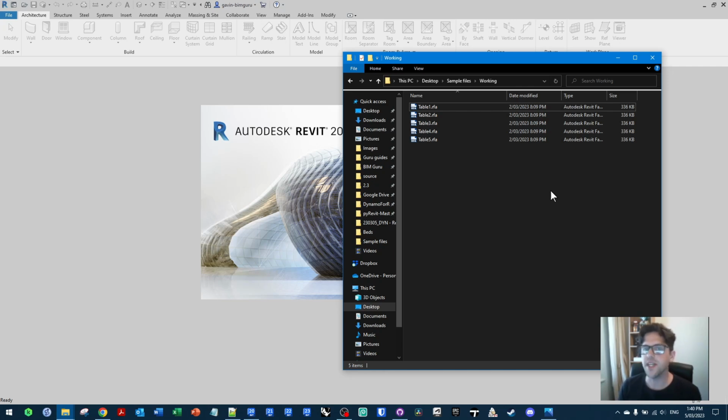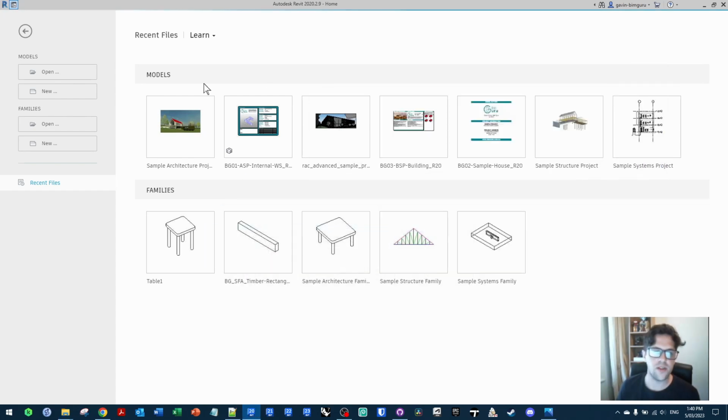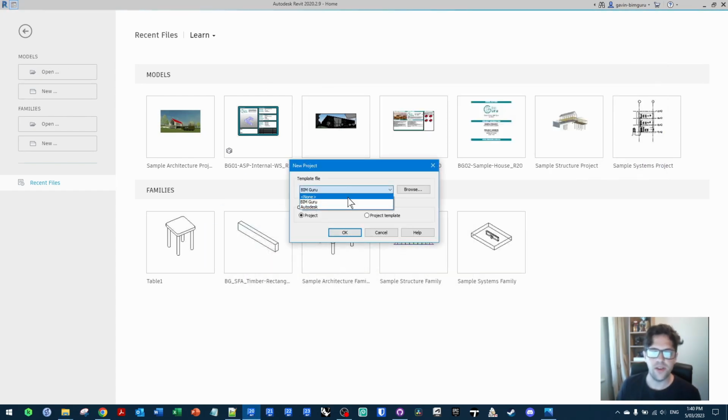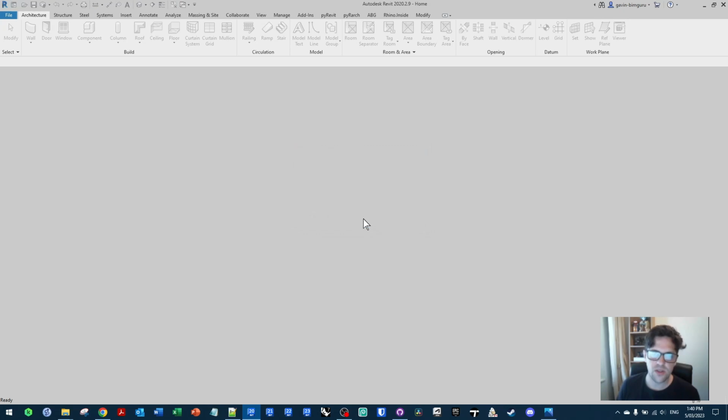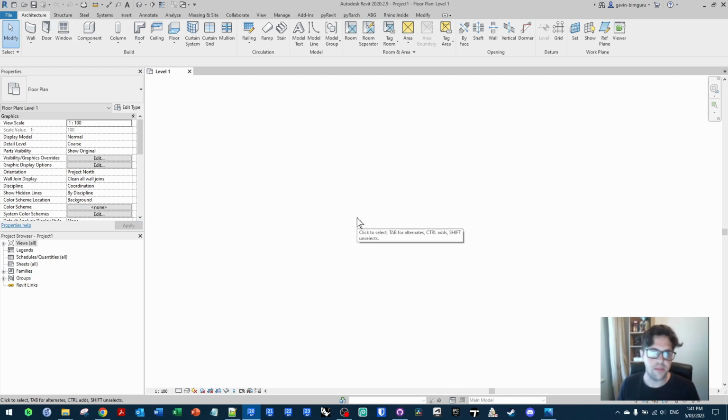There is one key limitation to be aware of with replacing parameters, and as far as I know, you cannot work around this, and that is if you have any parameters associated on an instance basis to an object that is in the model as a component that supports associated parameters, you know, those little equal signs down the right side of a parameter.